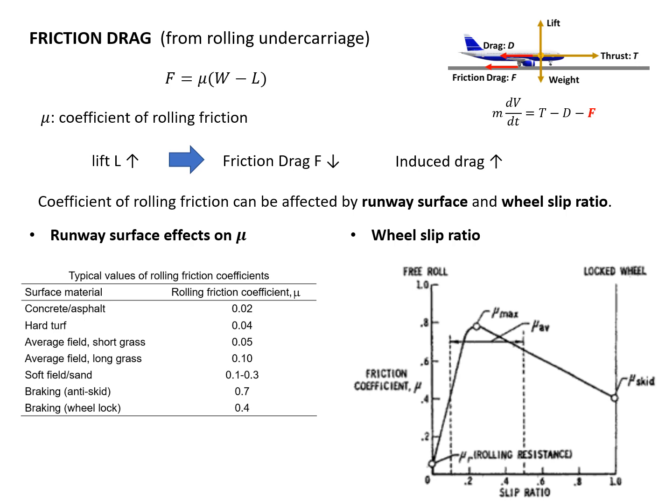And that's why when we do the brake, if we fully lock the wheel, it doesn't actually produce the largest friction. So that's the smart way of doing the brake. We have the anti-skid system, not only for aircraft but also for cars.